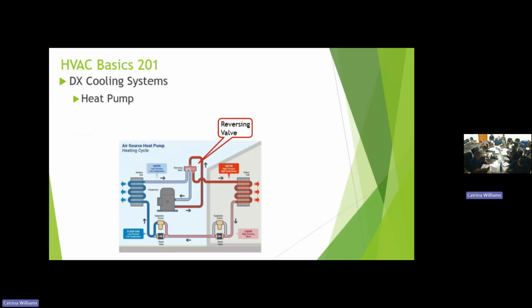I have a heat pump system in mine. And if you're ever around a residential condensing unit in air conditioning mode, you put your hand over that air that's coming out of it, and it's hot, it's getting rid of the heat from that coil. But when you turn on the reversing valve, now it's blowing that heat through the evaporator coil inside your house, and you feel cold air outside come out of it. Yes, very much so. And as long as the air is above absolute zero, they still work. They aren't nearly as effective in real low temperatures, but they do reject heat. That's the important thing.